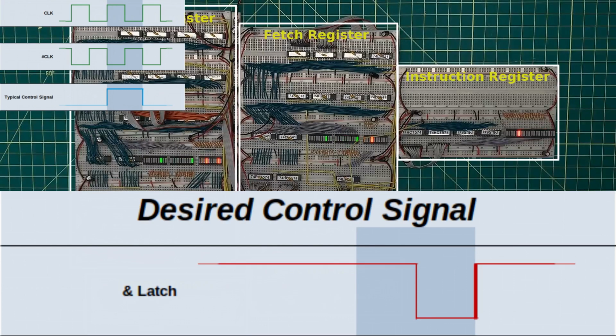We want to frame that such that the signal is high most of the time and then comes low right before it returns back high. And it's that rising edge that is going to be of interest to us. And then once it's been returned back to a high state, it's going to stay at that high state until it is required again.